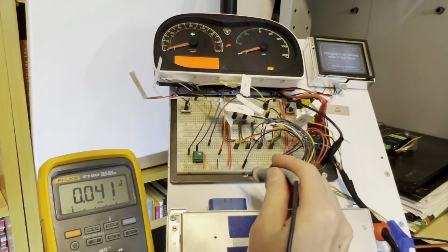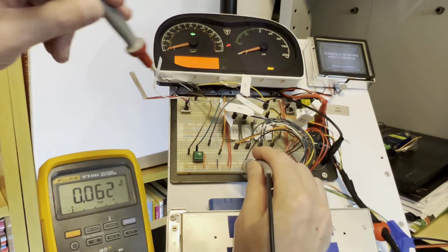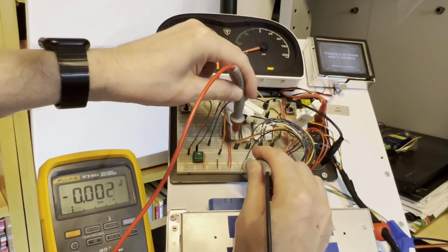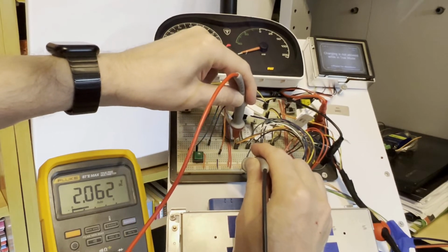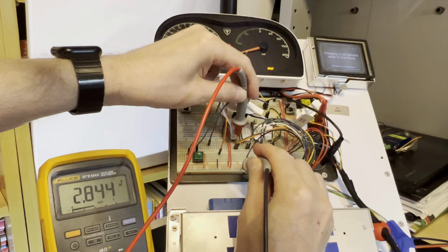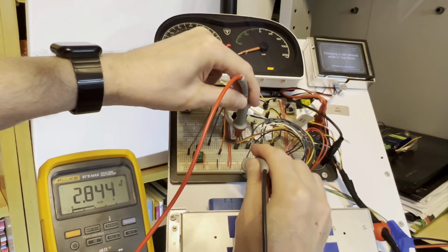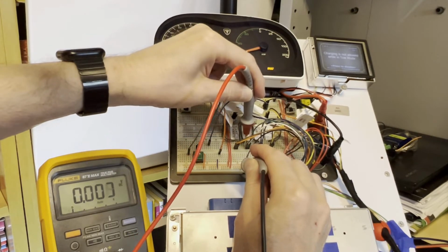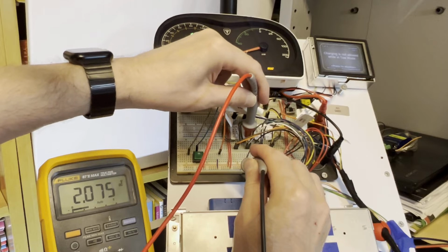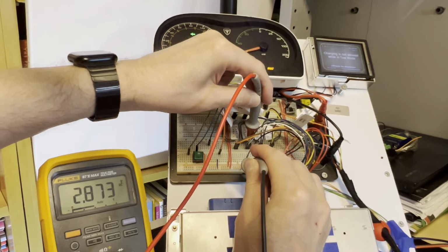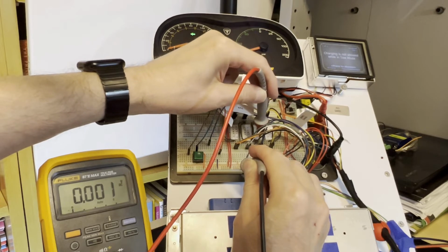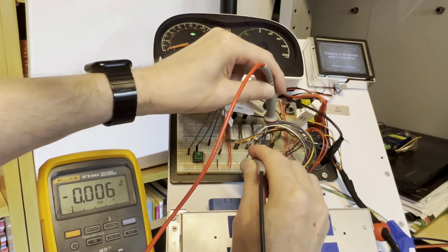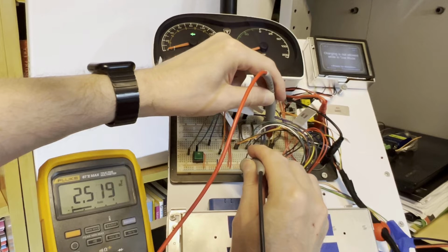Now let's look at the voltage on the CAN bus connections. Each bus has 2 signal wires called CAN low and CAN high. Compared to the system ground, on the first bus we are seeing around 2 volts on CAN low and 2.8 volts on CAN high. The second bus is showing about the same, while the other 2 are showing around 2.5 volts on both wires. The difference depends on things like whether the bus is active or not, and termination arrangements.